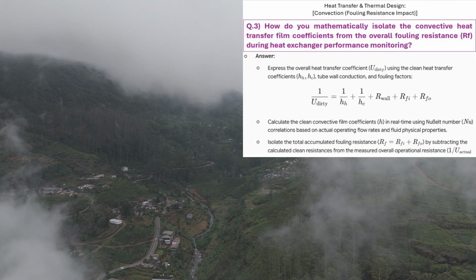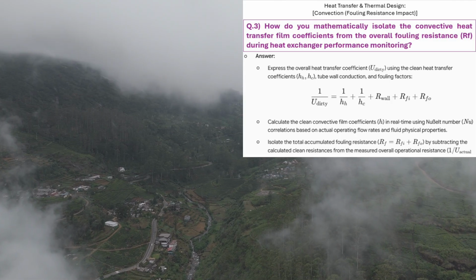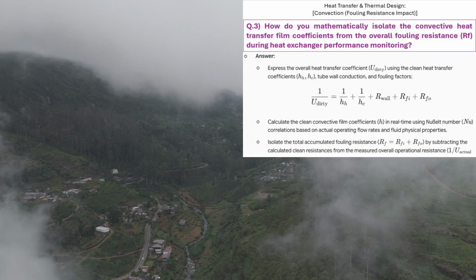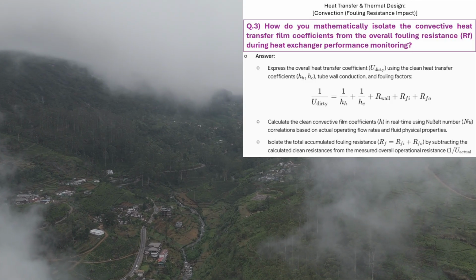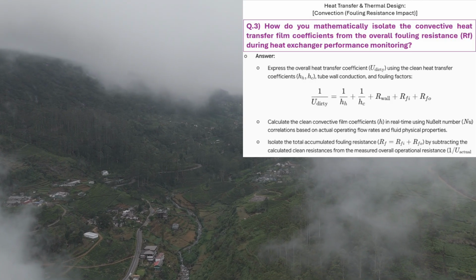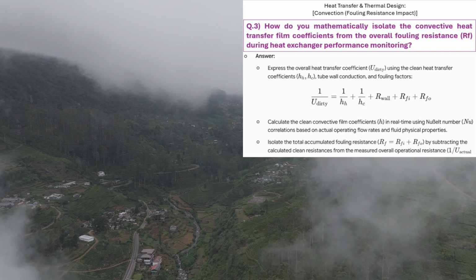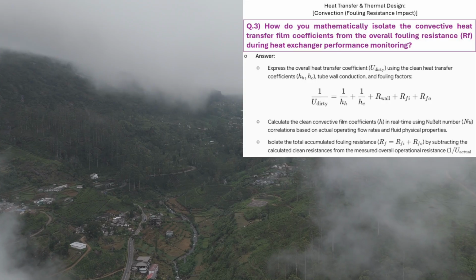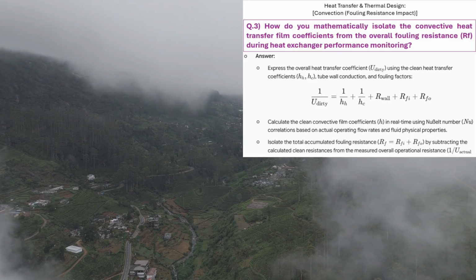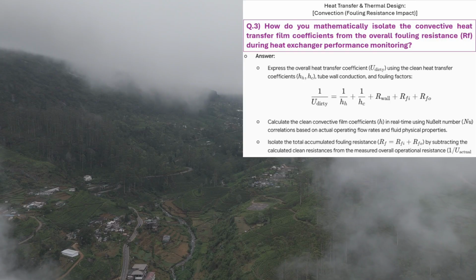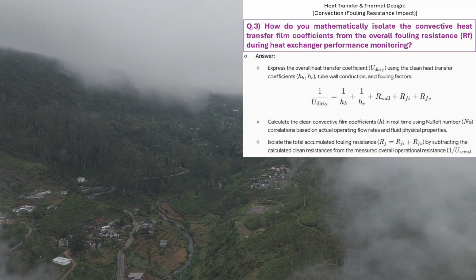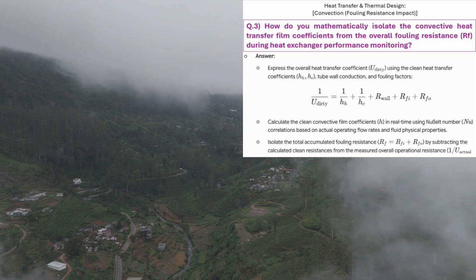And what about plate and frame exchangers under these turndown conditions? I apply an even stricter caution there. Plate exchangers rely entirely on inherently high turbulence generated by narrow, corrugated channels. They are profoundly less tolerant of operational fouling margins. Because even microscopic buildup chokes the channel. Exactly. A tiny layer of physical buildup combined with a slight loss of velocity destroys the shear stress required to keep the plates clean, causing the pressure drop to spike exponentially.